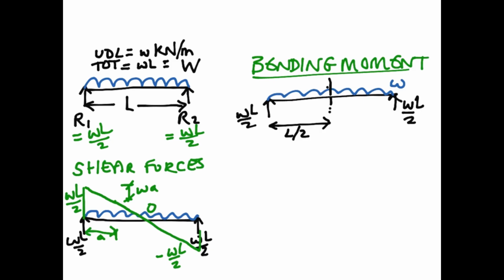So to work out the bending moment at a particular point, you're resolving all the bending moments to one side of that line. We could resolve to the left of that midspan and come to an answer, or we could go to the right of the midspan and resolve forces there, but you'll come to the same answer. It doesn't matter what part of the bridge you look at.